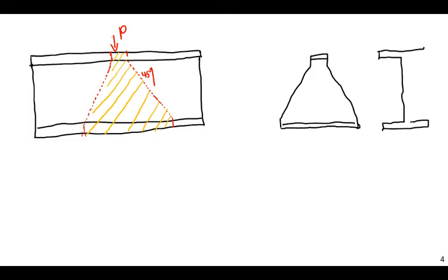So calculating the actual buckling capacity of this is also complicated by the fact that the edges will also want to prevent this from buckling, so it's more effectively braced, but this is still basically a column. This is a column with a finite cross-section, and this thing can buckle. So this is how webs are able to buckle. Even though they are continuously braced, they are still able to buckle.